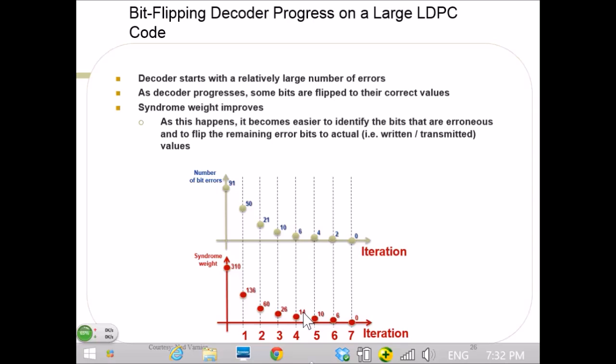You have to do a CRC on top of that to make sure that there is no miscorrection. If there is miscorrection, it happens due to a trapping set, so again you have to do different kinds of post-processing. Basically the idea is you're looking at the number of equations and seeing how many are not satisfied. Until all the equations are satisfied, you keep iterating that processing.